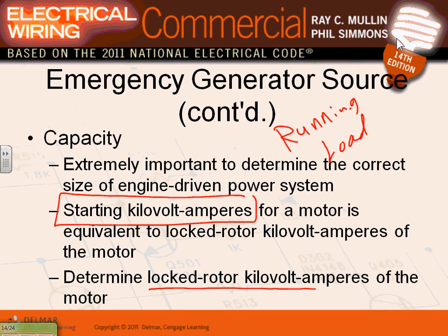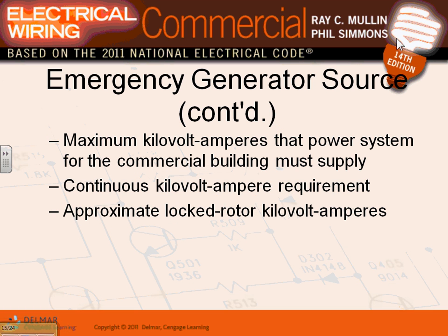A good engineer would always stagger the load, meaning you start this chunk with an auto transfer switch, another chunk with another auto transfer switch. What's the problem with this? Expensive. You have to have different auto transfer switches to start them at different stages. Okay, so that's basically sizing the generator.